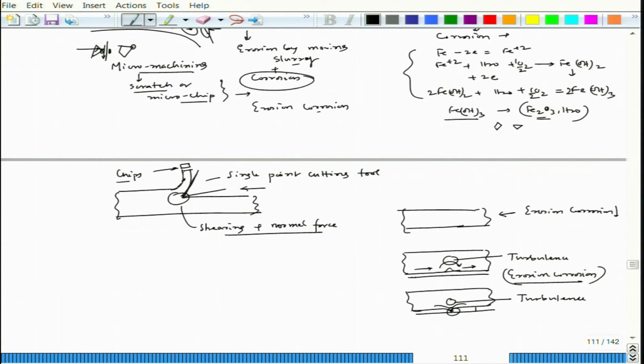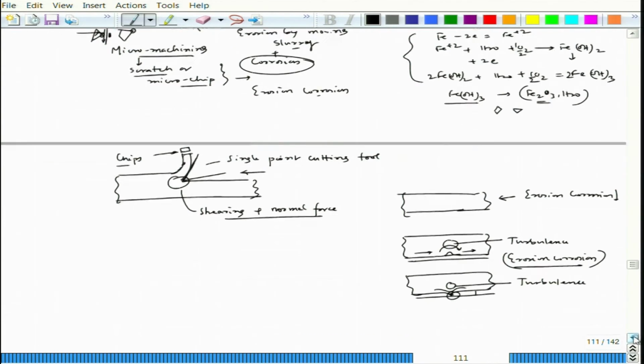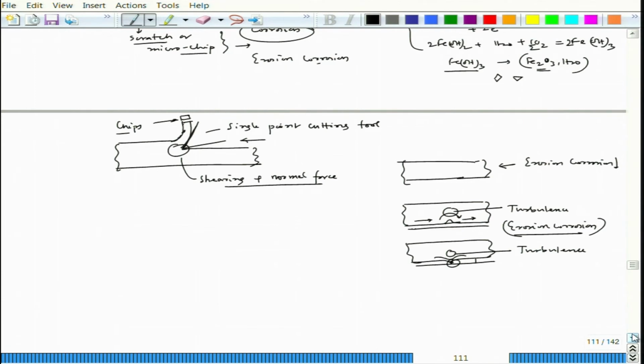In fact, this particular debris formation, that debris can also hit another portion of that pipe where the direction is changing, and that might lead to, if it is clean water, let us say there is no dust or something, because of the local erosion, those particular particles might form another small chip kind of thing, and that particular small dirt particle can also hit at an angle or direction change and can lead to a lot of erosion. Fine. So, this is a situation where one can experience such kind of defects or erosion corrosion situation.